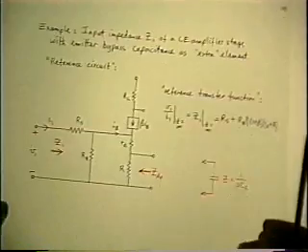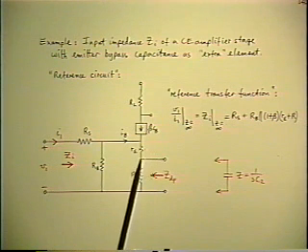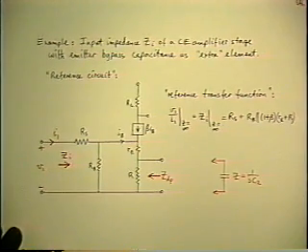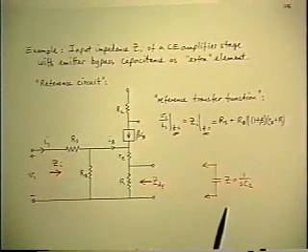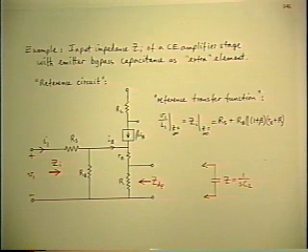Now I want to illustrate applying it to a self-impedance. For example, the input impedance of the same common emitter amplifier that we've had before. Obviously there's no need to show a separate example of applying it to a transfer impedance, because that's obviously the same as a voltage gain. But let's do it for a self-impedance, just to emphasize the fact that impedances are transfer functions as well.